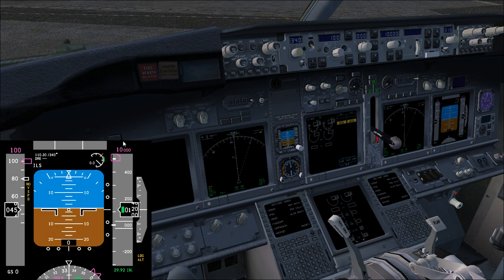The same indications are actually present on the altitude tape. Actually, the altitude tape is in hundreds of feet, and we have a window with the actual digital readout altitude of 115 feet now, and actually it can go from minus 1,000 feet to plus 50,000 feet above sea level.